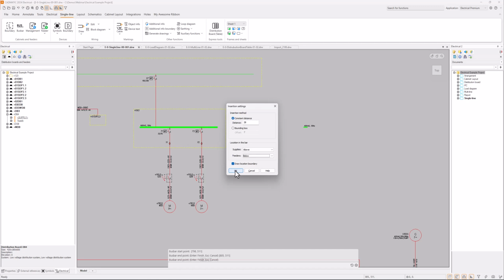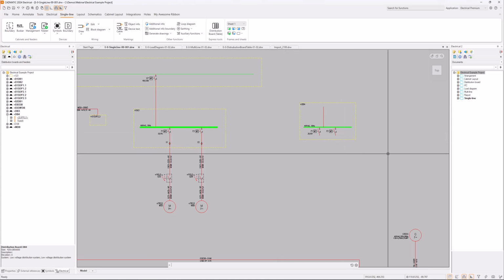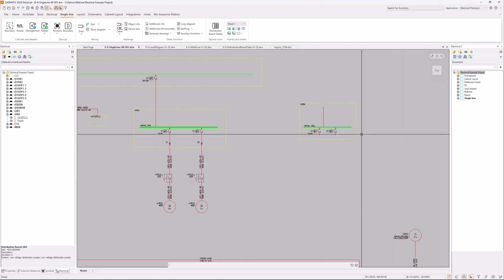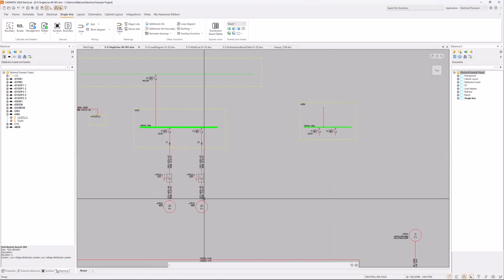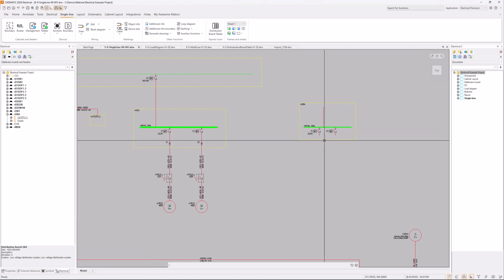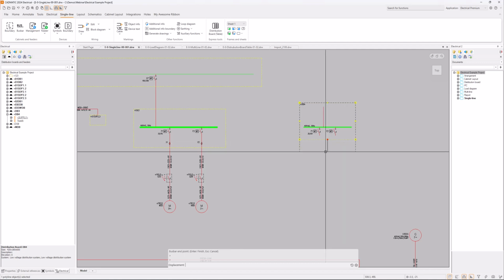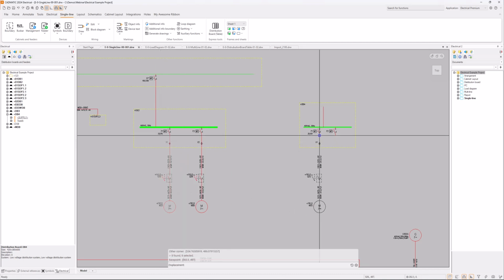And when everything is set, select OK, and it will be drawing the whole boundary, bus bar and the devices inside your cabinet. In this case, of course, it doesn't draw these motors, safety switches, or connection points. You can define those one by one if you like. Then you can copy things here, or then you can draw.